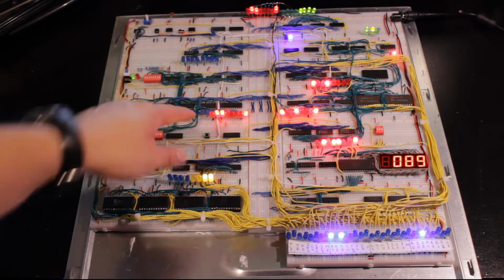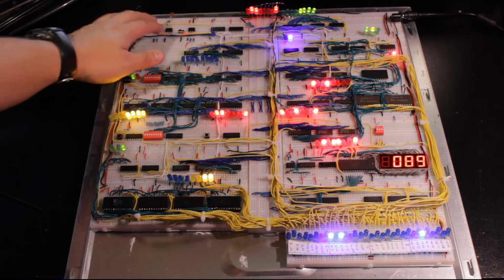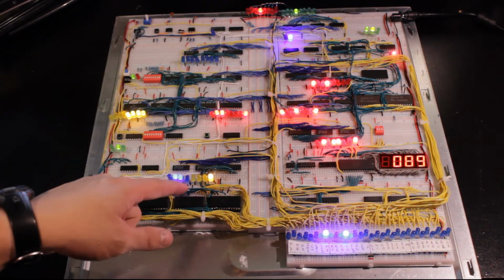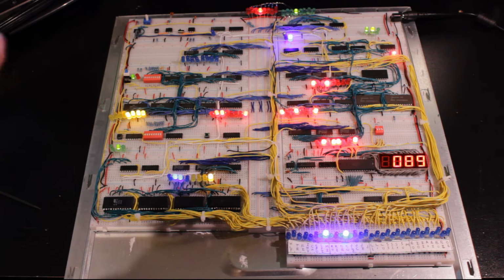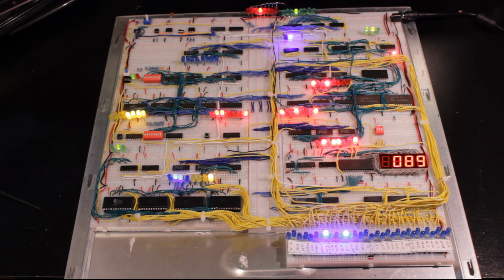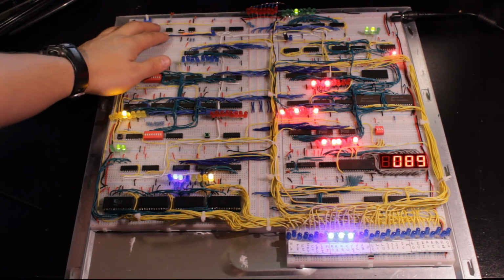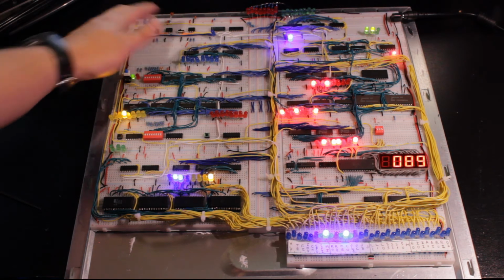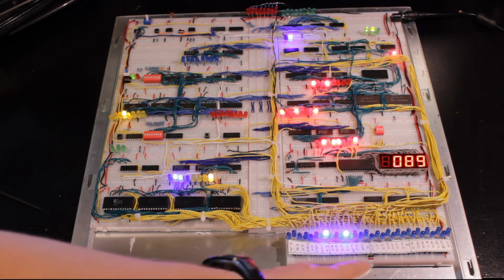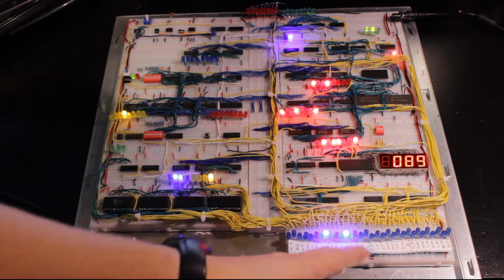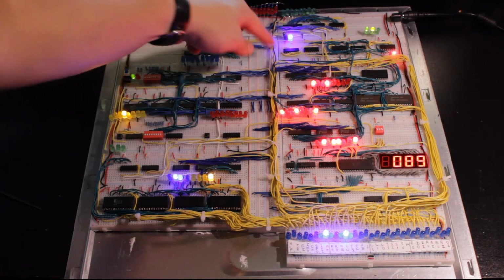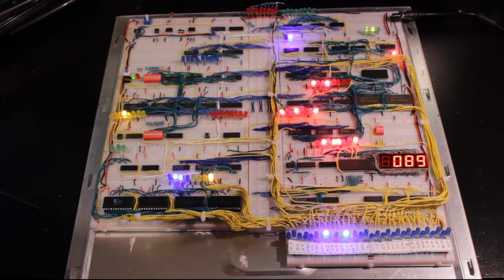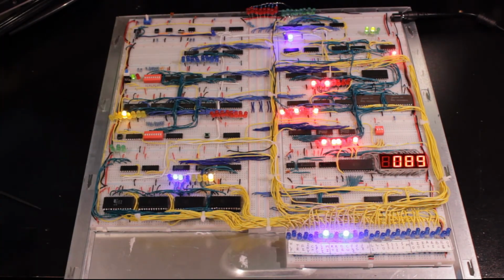And now we have our jump less than 0 instruction. So we're going to get this instruction in the instruction register. So now we have the instruction in the instruction register. We are executing the jump less than 0 instruction. It needs to fetch the pointer to the location in memory where we're going to jump. Okay, so it's got that. And you can see we just jumped because the jump less than 0 signal was true, and you saw the jump LED go on, and then we jumped to that memory location. And now we're starting the program again.